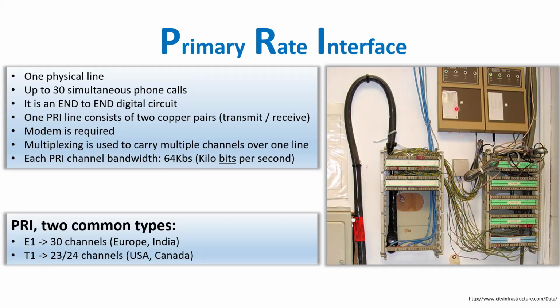There's one modem for T1. There's another modem for T1. So over here will be about 23, to be on the safe side. There's about 23 lines, and there's about 23 lines. And here's 100 lines just by the POTS. There's 100 line, 100 pair telephone cable. 100 pair cable, which is, remember, when we did the lab, it's 4 of those 25 pairs.